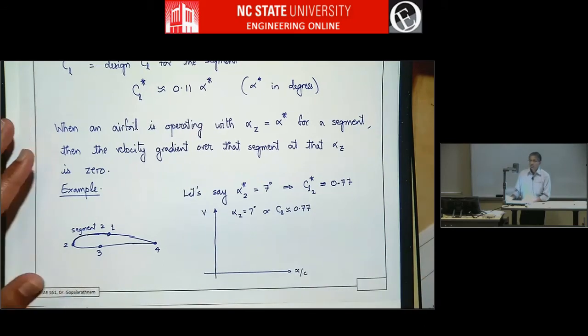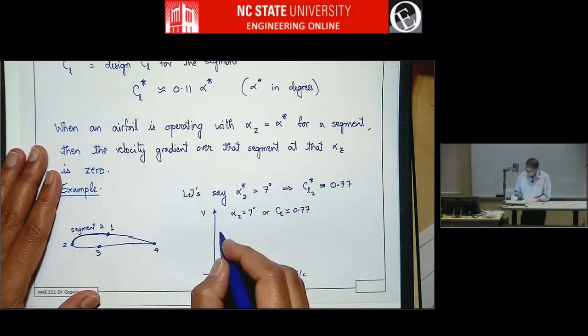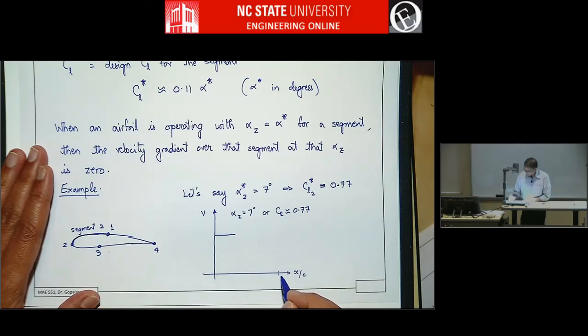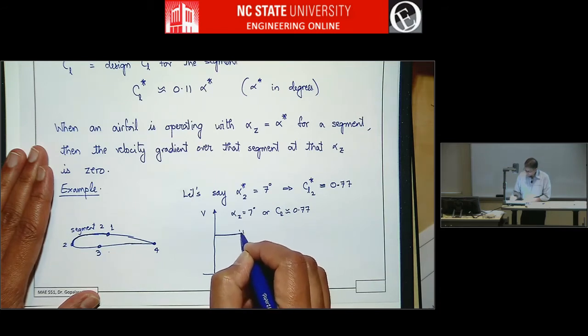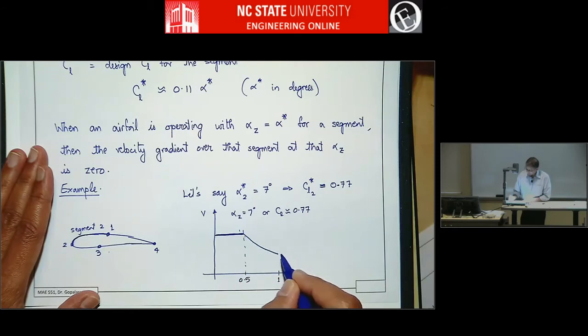if you design this airfoil and run it in Xfoil, because Xfoil converts the airfoil into panels, there's a small amount of discrepancy that will happen. But let's say you plot the velocity distribution in Profoil itself, where the velocity distribution is calculated exactly with conformal mapping. Then it'll turn out that this segment, let's say this goes to 50% of the chord, will have exactly flat velocity, and then it might go to something like this.